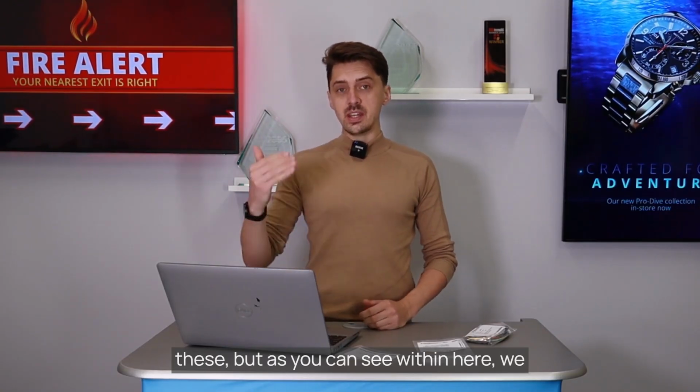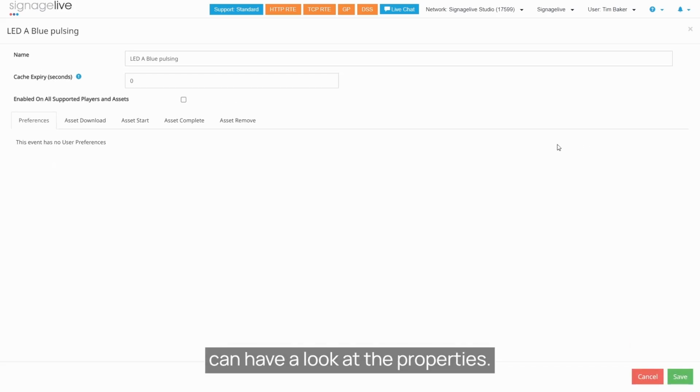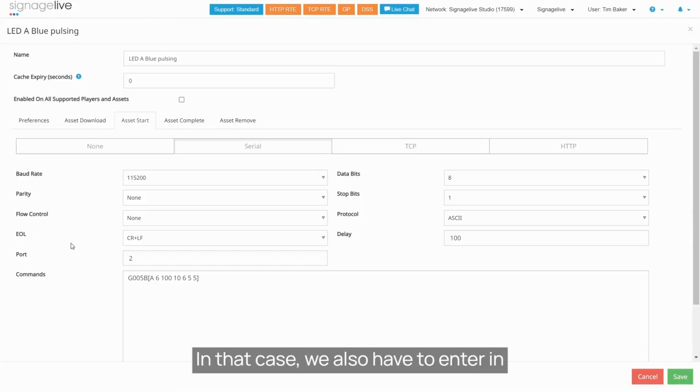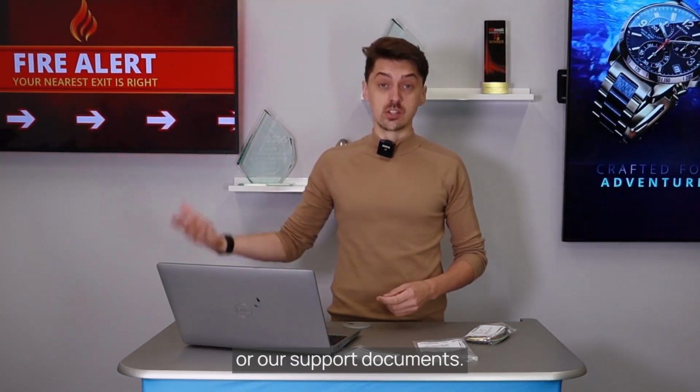As you can see, within here, we have pre-configured different content styles or color styles. So we've got red pulsing, blue solid, red solid, all of that. If I go into each one of these, I can have a look at the properties. These are all configured based down to where the asset starts. So for example, when this blue image starts, we've configured that to display blue color. In that case, we also have to enter in things like the baud rate, the parity, flow control, all of the bits and pieces. You'll get all of this information from Nexmosphere's page or our support documents.